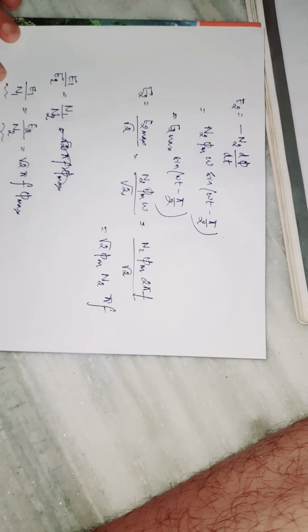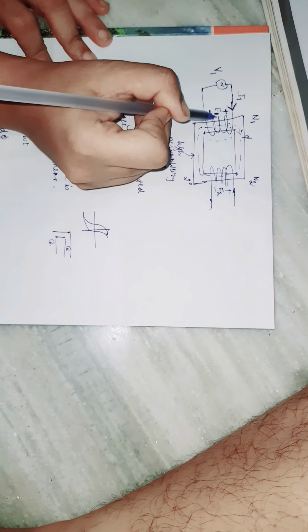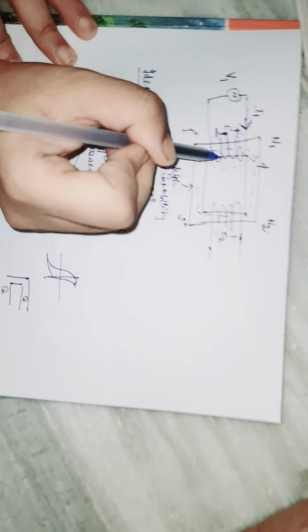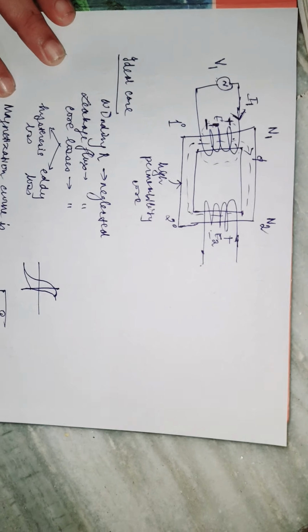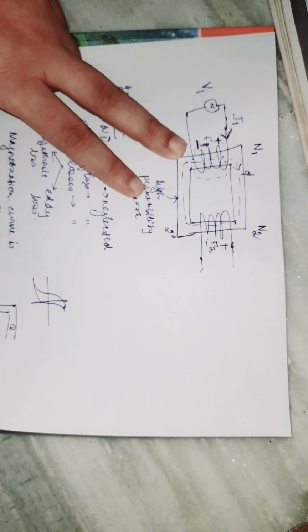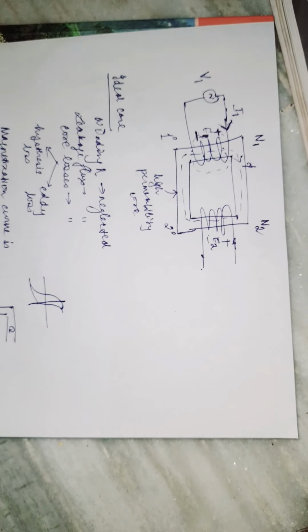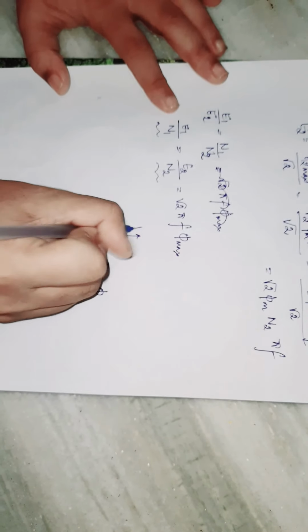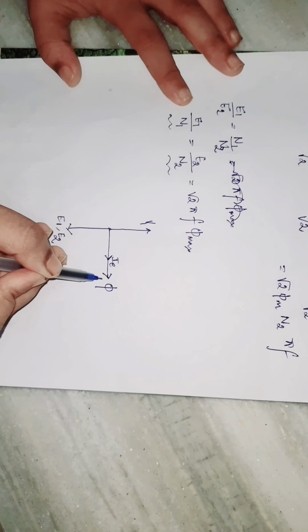And about V1, let's also plot V1 in this diagram, because initially I told you that this is V1 and this is our current. It links E1. But as this current is used only to magnetize the core, and it is very small, V1 is equal to E1. But since we are considering the magnetic aspect, we will show it in this direction, because V1 produces flux.